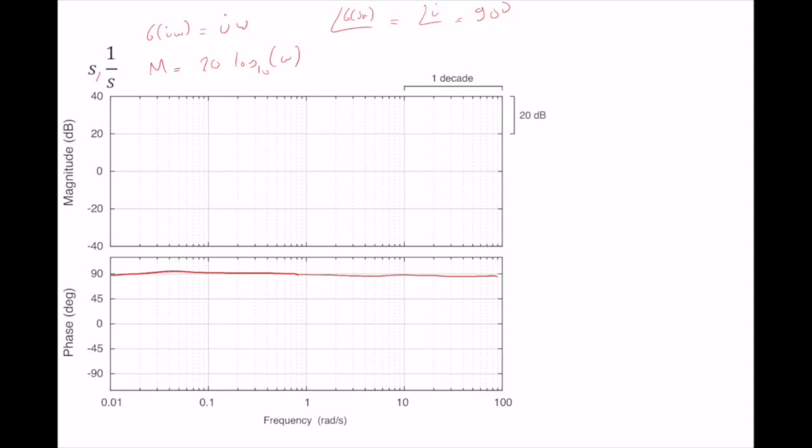If you look at the magnitude, it says logarithm, but since frequency is also in logarithmic scale, let's say this is log omega, let's consider it as a different variable. It's also a line in the magnitude axis, right? It's a simple line. So for omega equal to 1, the magnitude is equal to 0. For omega equal to 10, it is 20 times 1 decibels, so it's 20.